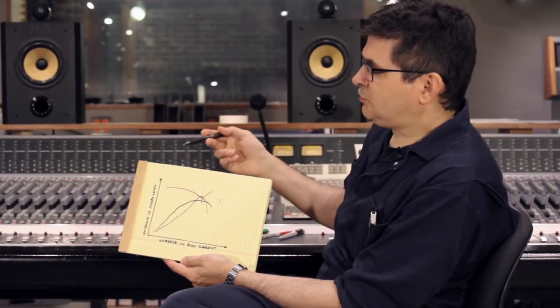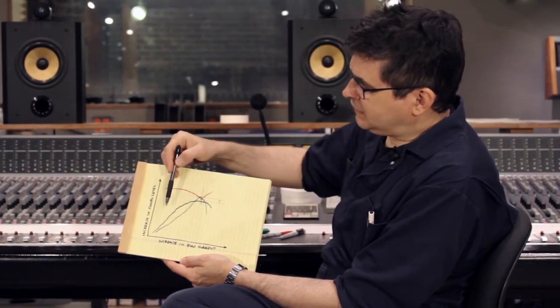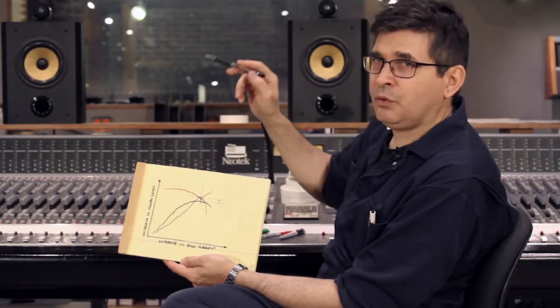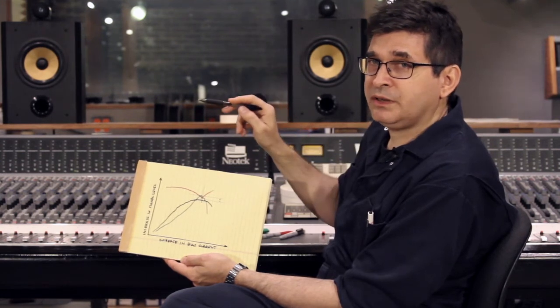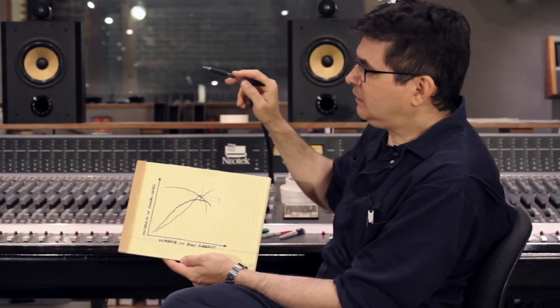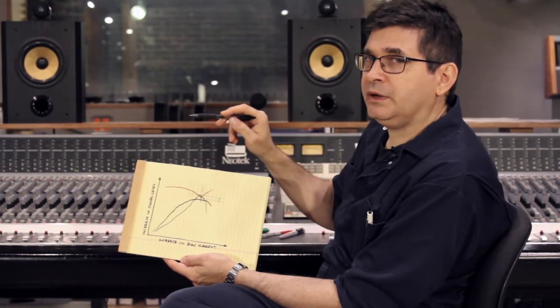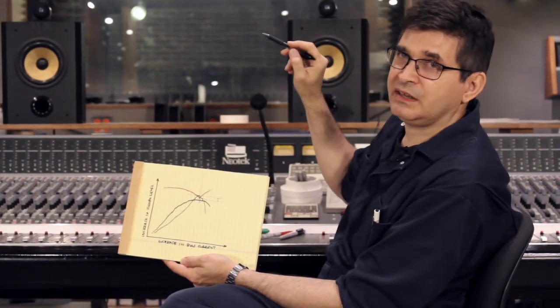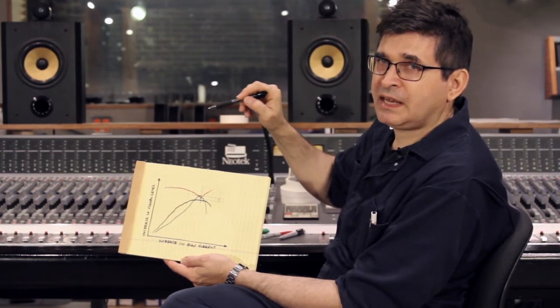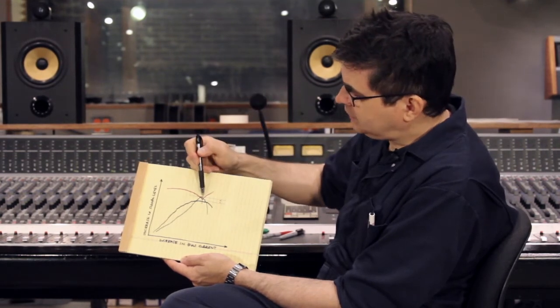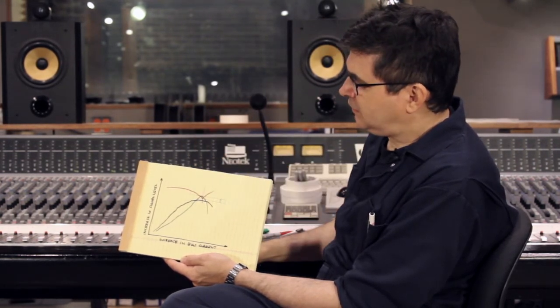So you could set the machine up to be recording, say, a 30 or 40 hertz tone, and then gradually increase the bias, and you will hear the noise floor begin to drop. You'll hear the noise and distortion components of that low frequency tone disappearing, and they'll reach a null point, and then as you increase the bias you'll hear them increasing again. And you'll just rock the bias control back and forth until you've satisfied yourself that you've found that point, the low point on that curve of the noise and distortion components,